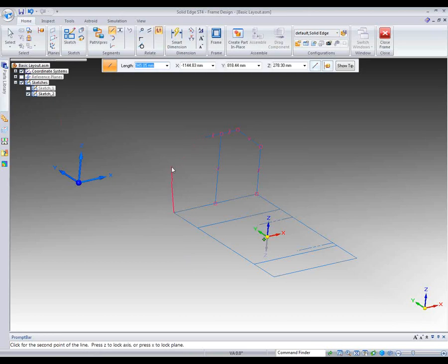And up that one. Now this time, because I've got a height here, I don't even need to type in a height. I just say to the end point of that, it'll make that the same. Pick my plane and lock onto there. Now I want to have the same down this end. So again, it's a matter of just going up in the X to that height. I want to be on the plane here to there, across in the X to that point, lock onto the plane again to that point, and then in the Z straight down to the end there. And you see how it all locks up onto the edge.